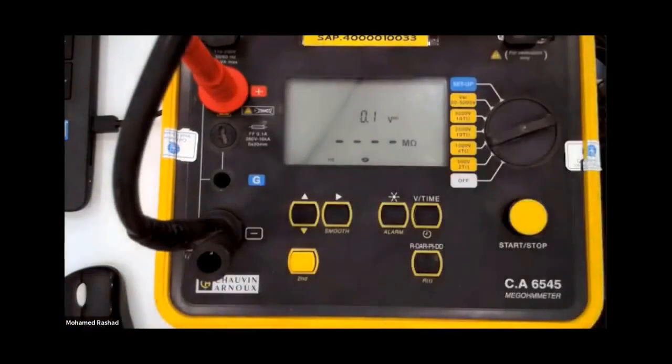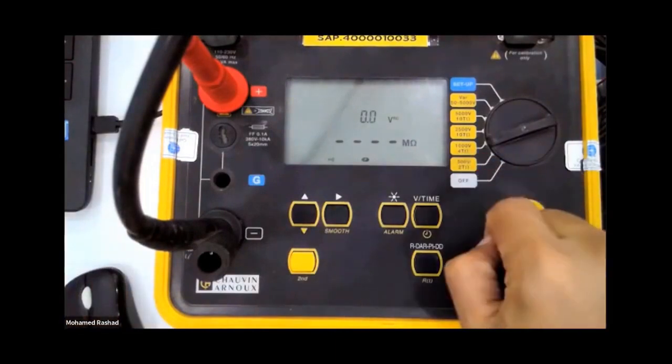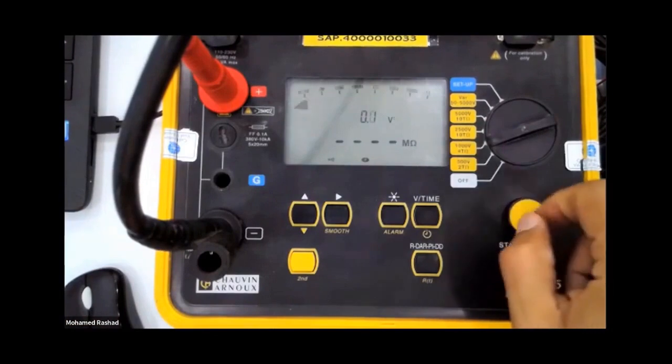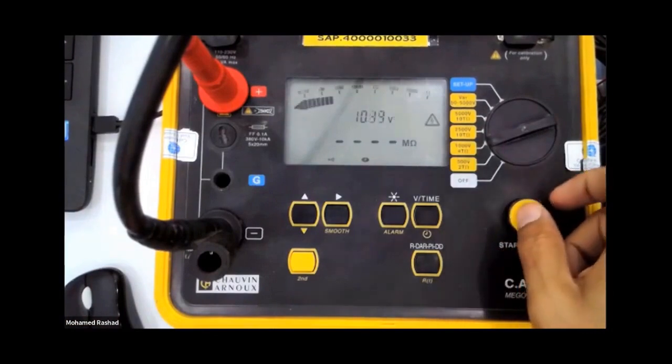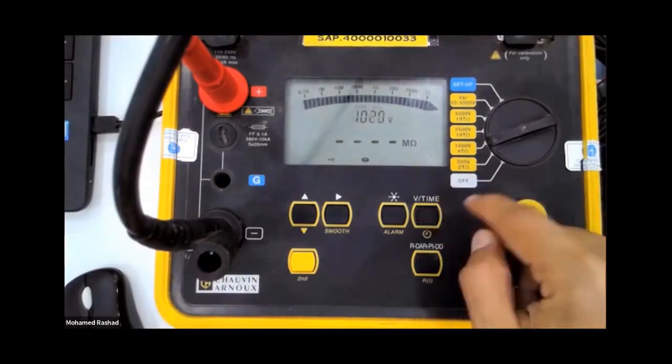Beautiful, guys. Nice. Okay, how much do I want to inject? I want to inject now between the primary and the ground, between the primary and the secondary, and between the secondary and the ground. So how much will I inject now? 1000 volts. So I select 1000 here. But before I press here, if I press like this now, it will start injecting. And I start by wanting to see, so I press here like this to see. And then I go back again.